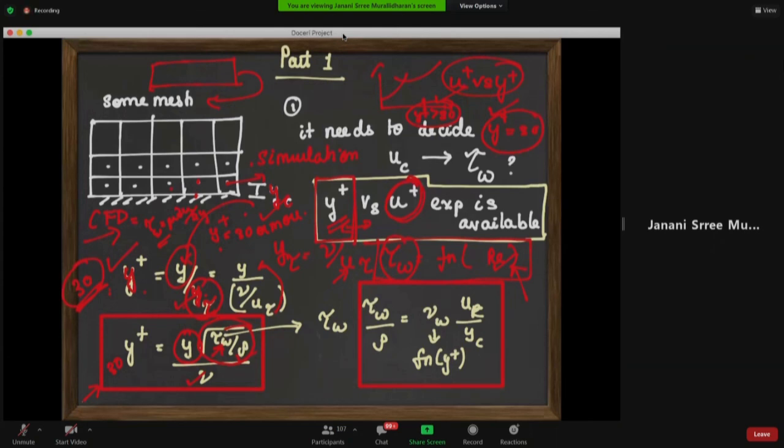It's just a first round of trial to understand how critical this y plus value is to the accuracy of your result. So from laminar, you move on to turbulence, and you will see how the velocity profile has changed because it's turbulent flow. And the importance of y plus has been discussed here, which you can use to check the accuracy of your simulation. Okay, so we'll stop at this point, and if you have any quick questions, I can take them before we go to your laminar flow through a tube tutorial.